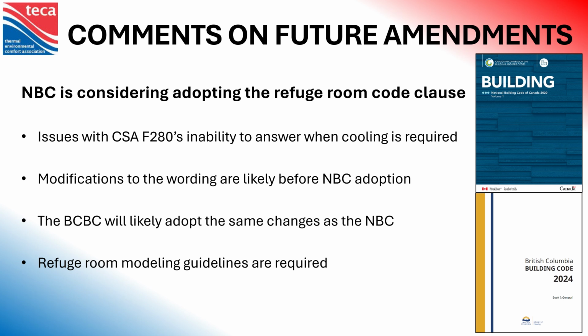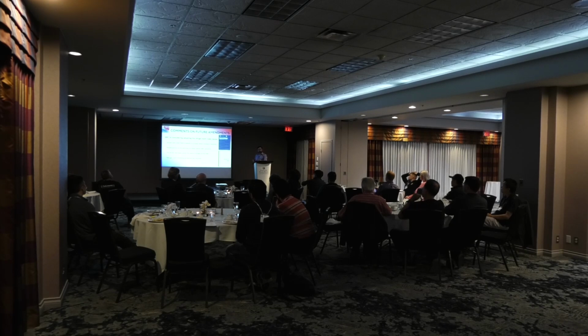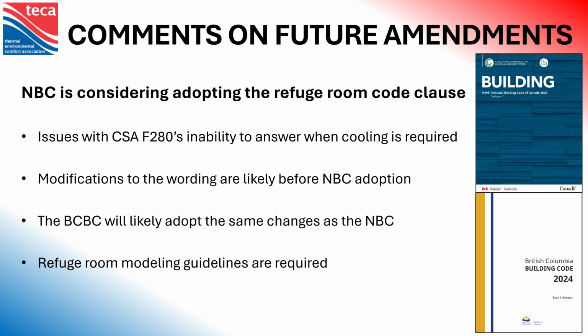I believe that the folks in BC are going to be paying very close attention to what the National Building Code accepts for changes, and I expect that they will adopt similar language. But I think one thing that is also really important to keep in mind here is that there has to be some sort of guideline or standard to model refuge rooms and determine what the results are with the CSA F280 calculations and when it is actually telling you that cooling is not required.